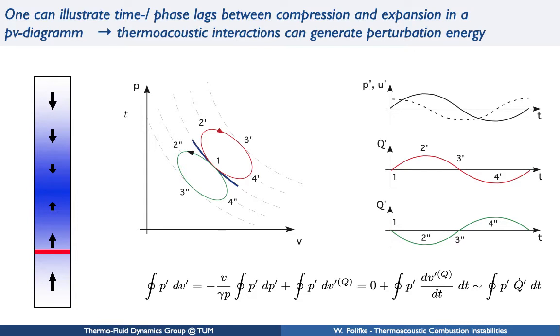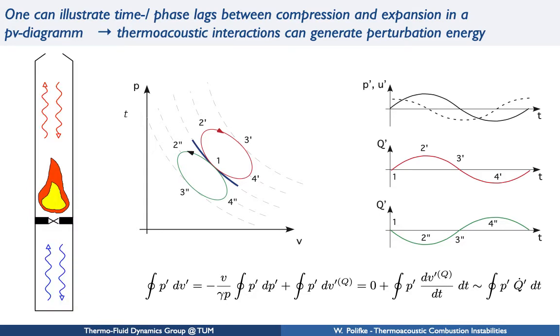And it follows that a little perturbation can get this little thermoacoustic engine going, and it generates more and more acoustic energy, which means that the fluctuations at the heat source become stronger and stronger, which means that the generation becomes stronger and stronger, and this whole thing can go through the roof, develop tremendous amplitudes, and blow up your combustor or your heat release rate. Because, I haven't mentioned this, but I should do this now, of course, a Rayleigh tube is just one example.